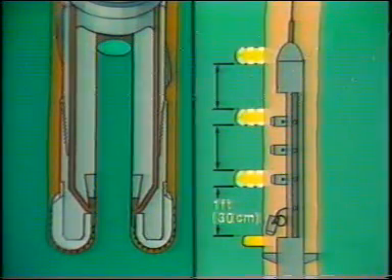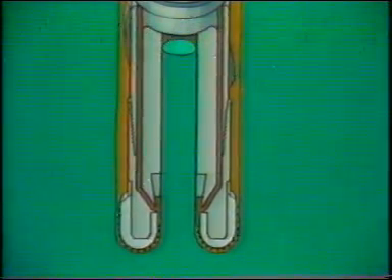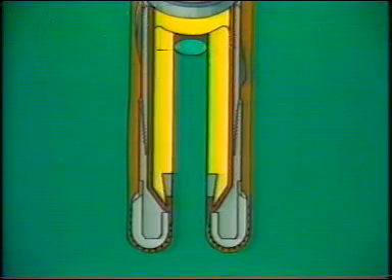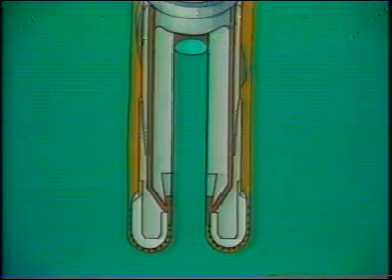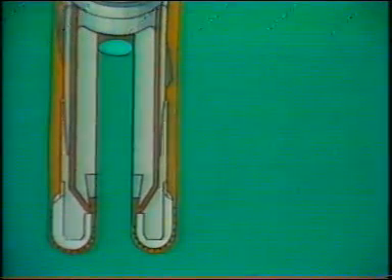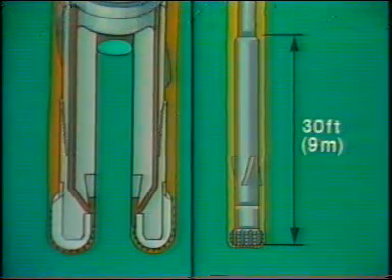The conventional coring device consists of an inner and outer barrel, approximately 30 feet or 9 meters in length. The barrels may be joined in multiple lengths for increased length of core recovery. In the J field, for example, it was common to run 3 lengths at a time. The bit is attached to the outer barrel. Conventional core barrels are typically 3 to 5 1/4 inches or 7.5 to 13 centimeters in diameter.